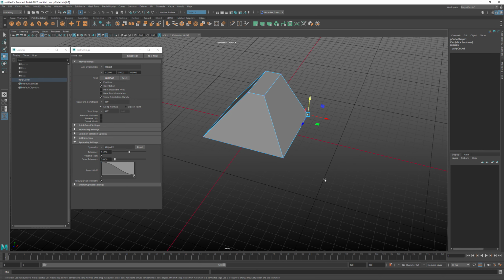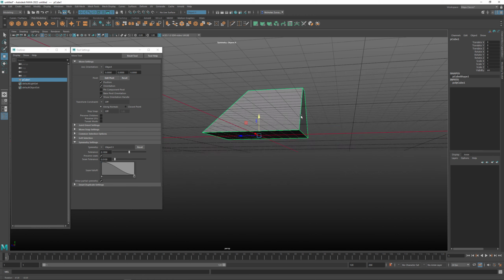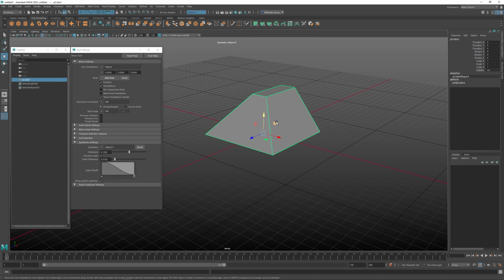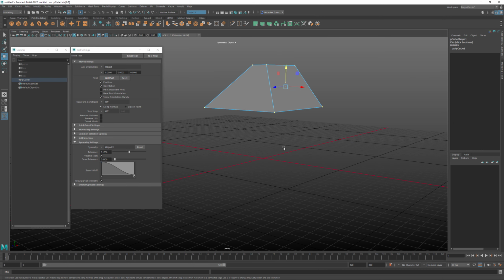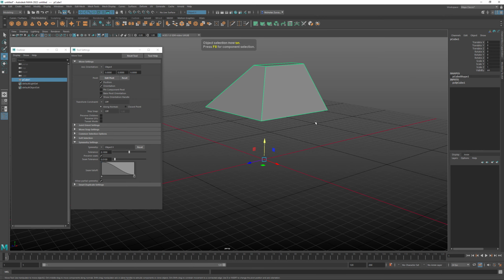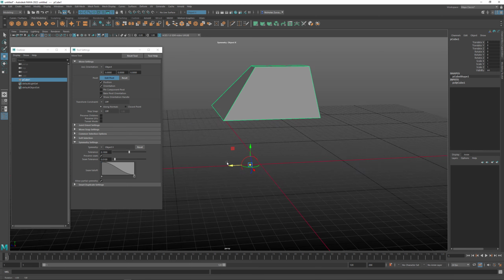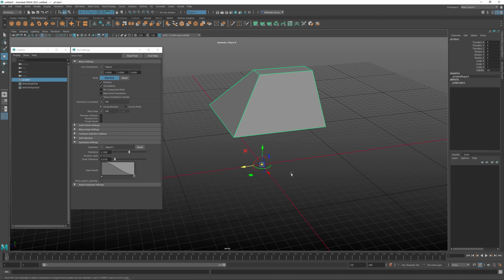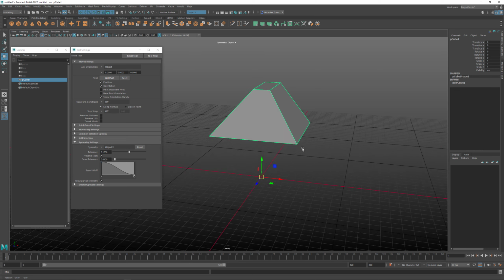The other thing to note about this is if we go back to object mode out of component mode, we are moving the vertices. That doesn't change anything about the object's location. So you can see the pivot point for the object is still set in the world origin here. And as we move vertices around, if I hit F9 or we right click on here and say vertice and I raise the entire object up, the pivot point for the object is still going to stay. So we can hit F8 to go back into object mode, and you can see that our pivot point stays exactly where it's at. We've looked at an earlier video, if you tap D, you can move the pivot point around and you can re-snap it and things like that. But moving these components does not change anything about the object space or the object orientation.